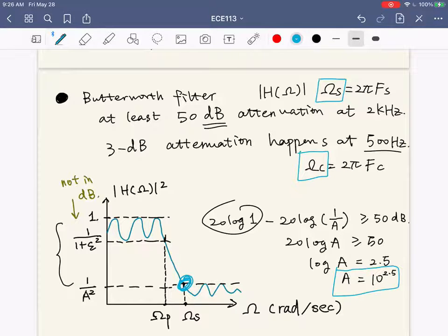Why isn't it 2 pi Fc over Fs, if the Fs here is the sampling rate? I would say it is because hertz is originally cycles per second, and your omega is radians per second, so they differ only by the 2 pi factor.